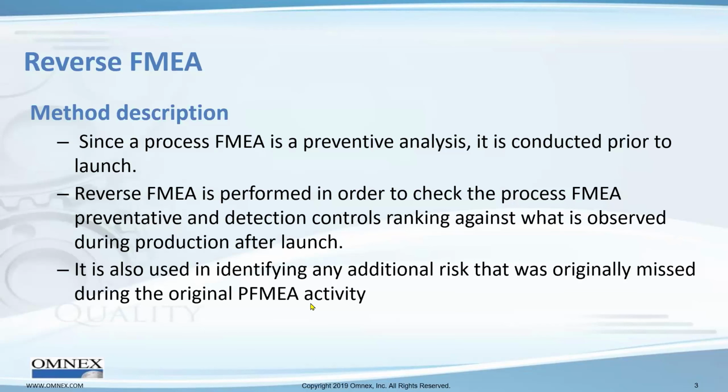Now, also, as we have our team out there going through the process, we're supposed to be taking what was identified in the PFMEA for, say, OP30 and making sure that what they identified as potential failure modes, we don't see anything that we feel is additional. So we're evaluating what the PFMEA saw as potential risk. And as we go through the line with a closer set of eyes, a new set of eyes, we're going to focus on whether they missed some potential risk activities.